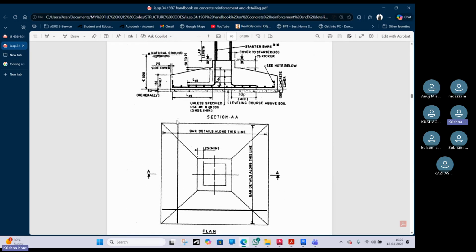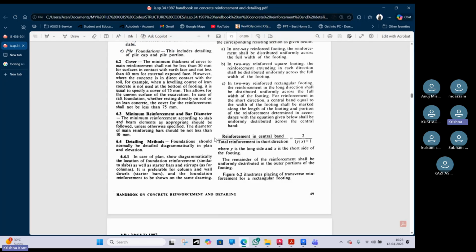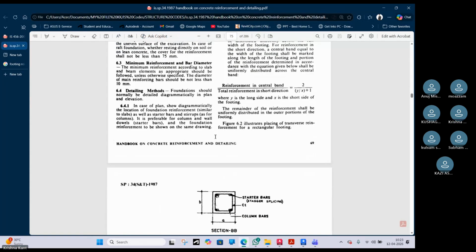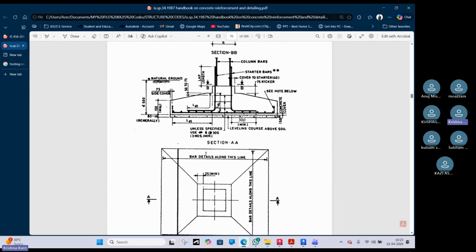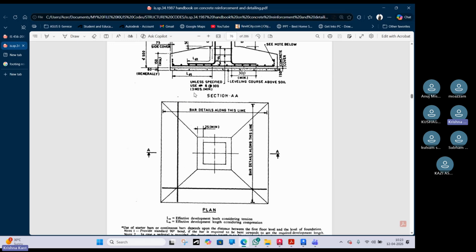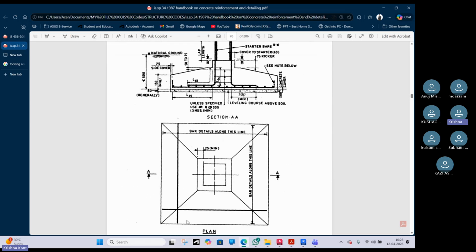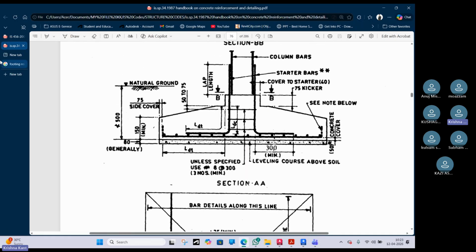so basically in footing, even in the slab, in the floor, there are two bars. One is the main bar, another one is the secondary bar, or that we call as distribution bar, okay. So what it means, main bars and distribution bar: when the slab or the footing is having one side main bar, the other side will be a distribution bar, which is shown over here in the section. The dotted one is showing basically the distribution bar. Okay, it helps in supporting the main bars.